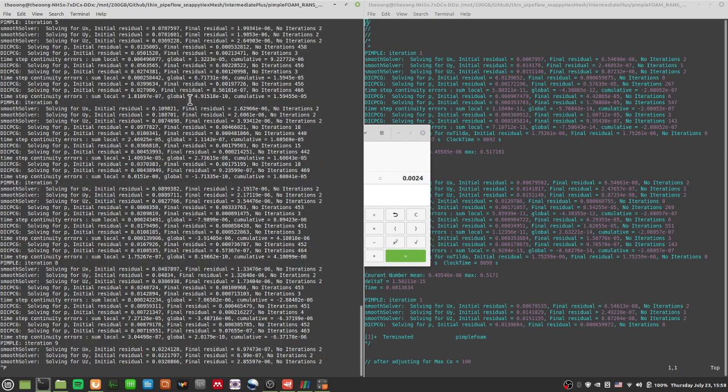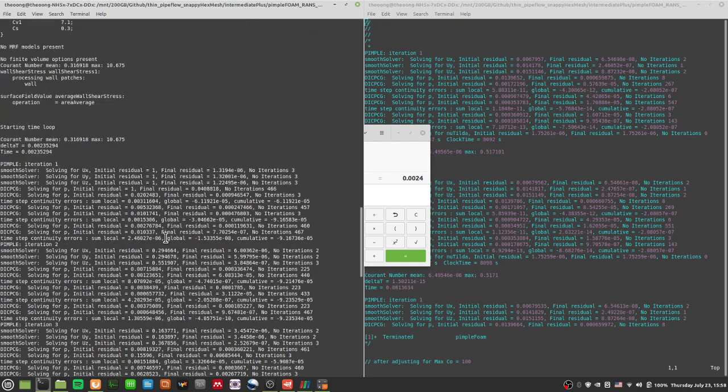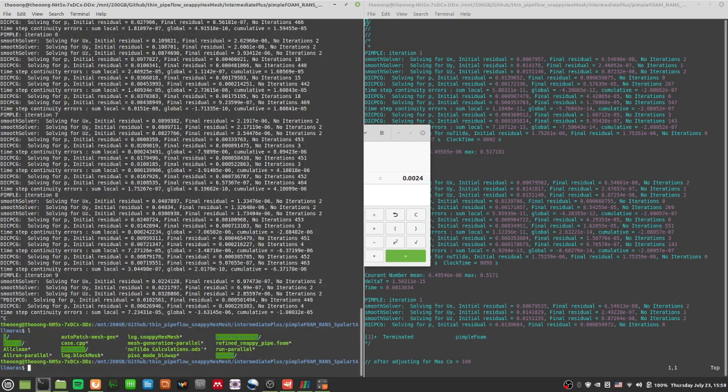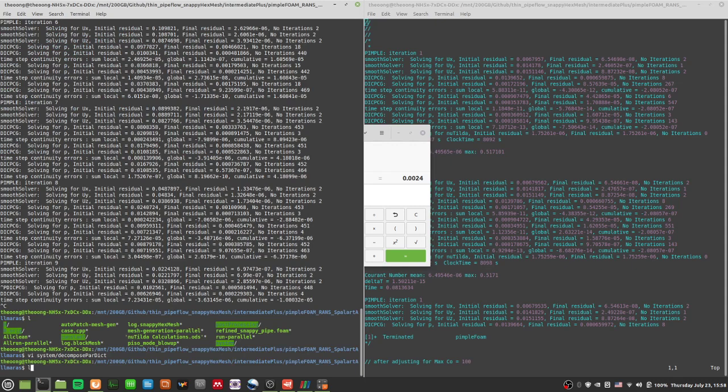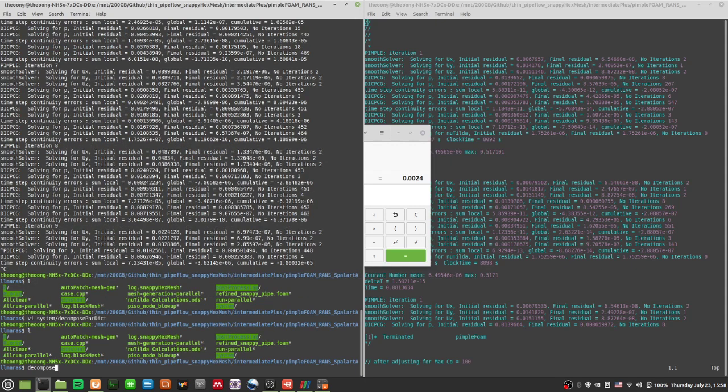Okay, and you know what? Maybe I'll stop for now. I'll pause this. Let's do parallel running, just to make it faster. Let's vi the system decomposeParDict. We have a scotch method with 4 subdomains. I would like to increase to 8. So let's run decomposePar.